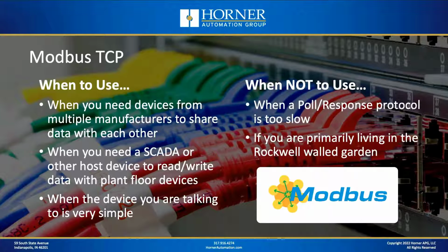And if you're primarily using Rockwell products almost all the time, then you may not want to use Modbus either. Well, what happens if you're using Rockwell and there's a device out there that you need to talk to that only talks Modbus? You can still do that. Rockwell does support an add-on instruction to do Modbus, but it's not ideal in the Rockwell world for sure.